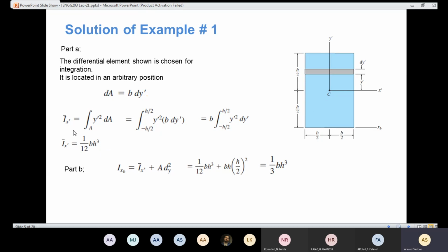So the only thing that is going to change, here we have h cubed. When I'm going to determine the moment of inertia about y here, I'm going to have the same answer, except that b is going to be cubed and h is going to be only h. So the moment of inertia about this axis is going to be like that, similar to this one.